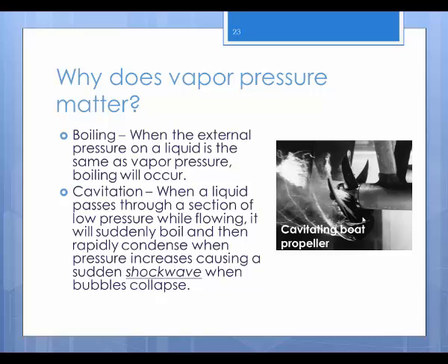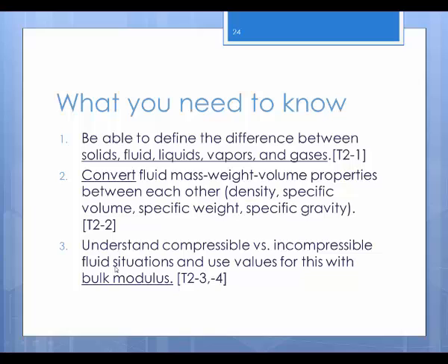Very damaging. So when you're designing something like a propeller, a pump, anything that's going to have changes in pressure, you want to know what the vapor pressure of this fluid is that I'm pumping, moving, spinning, and am I ever creating a condition where the pressure inside is going to, even for a minute or even for a small area, have a pressure lower than the vapor pressure? Because if that's happening, then you need to adjust your design so that you don't create these bubble shock waves. All right, so that pretty much covers this whole topic area.